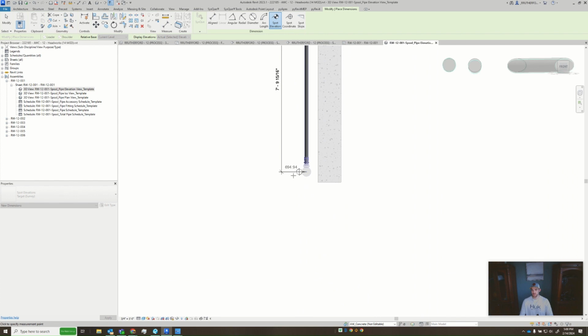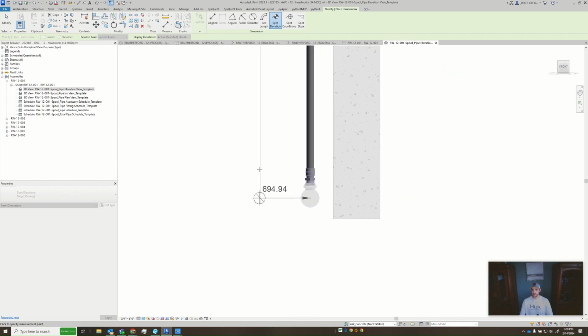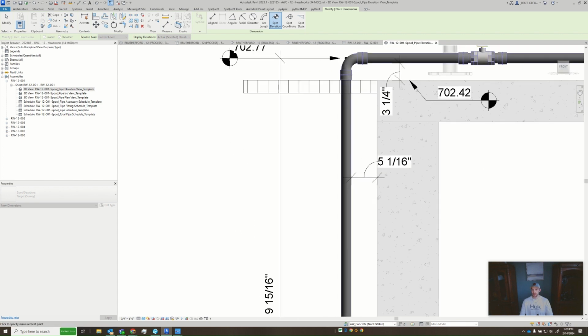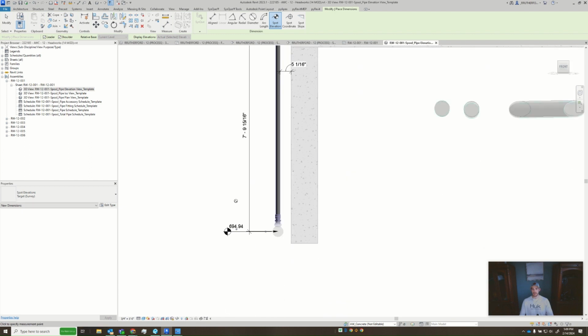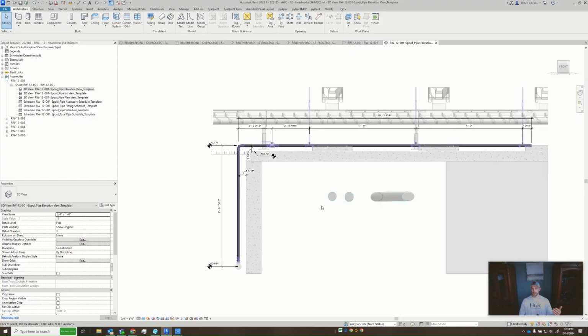And a nice thing is, once you've hit that first click, similar to adding a tag, it locks it into that plane. And one thing I like to do is find the center of another one that's above it or in the same line. I don't have to be looking at the one that I'm setting. Click enter, and now both of those are basically on the same line. It just, again, it's a visual thing, but those visual aspects add up to an overall good looking drawing.